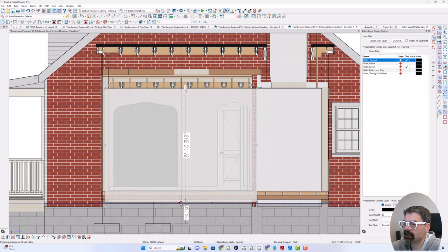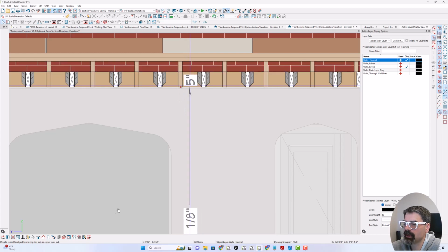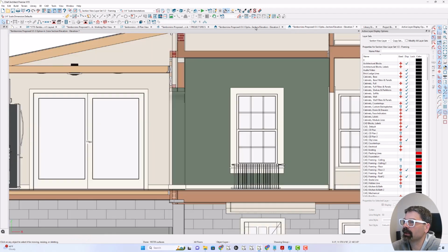I don't necessarily have to bring up the bottom, but if I bring the top to the ceiling joist section, and then build my wall studs, you'll notice that my elevation, my plate goes right beneath the ceiling joist as I want it to, because this is the line of my brick right here.